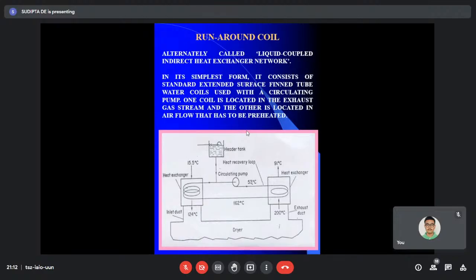Why fresh air? Otherwise, the oxygen percentage will continuously decrease in the confined space, because people occupying the space are continuously taking oxygen, and not only people but other living elements also need oxygen. So you have to replace that air. Though its temperature is effectively still higher, you have to reject it due to oxygen concentration management and other issues. Some odor may also be created by continuous use. If you don't replace it with fresh air, these problems will be there.